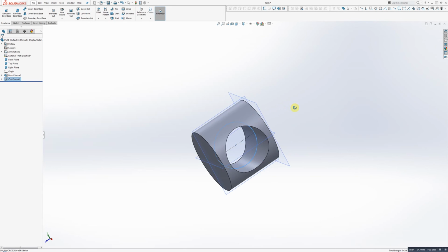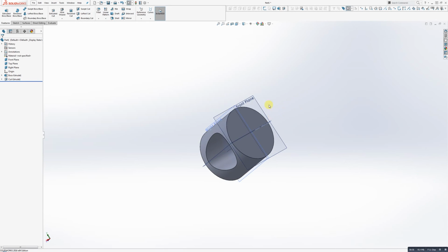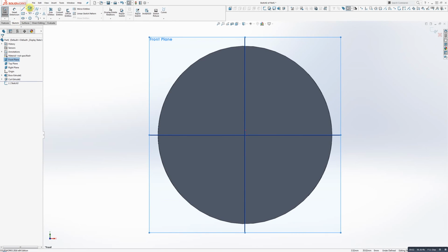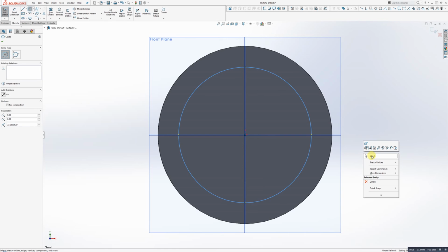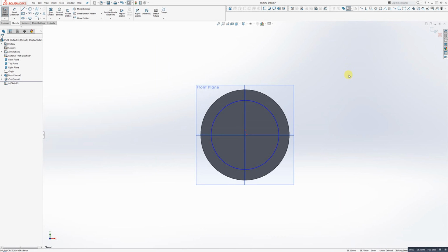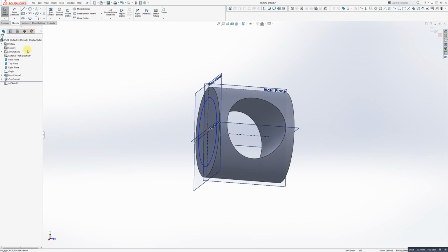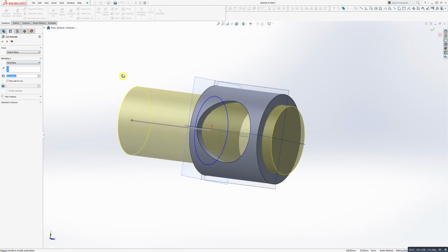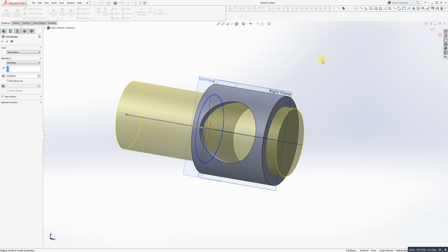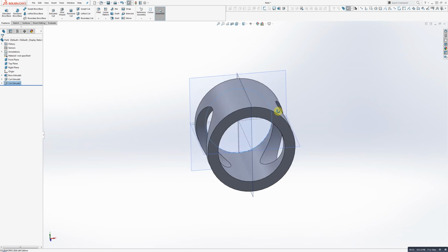Want to cut a hole out of this side? Do the same thing. I'm going to do it quickly this time. Right click, create a sketch, normal to, grab my circle, line it right up with the origin, and go like that. I'm going to right click and hit select to deselect the circle tool, as opposed to hitting escape. I'll go into 3D and look at my work, go over to the features, grab my extruded cut, and quickly set it to mid-plane. There she goes. I'll double check that it's following through to the other side, hit the enter key to approve that, and then we're good.